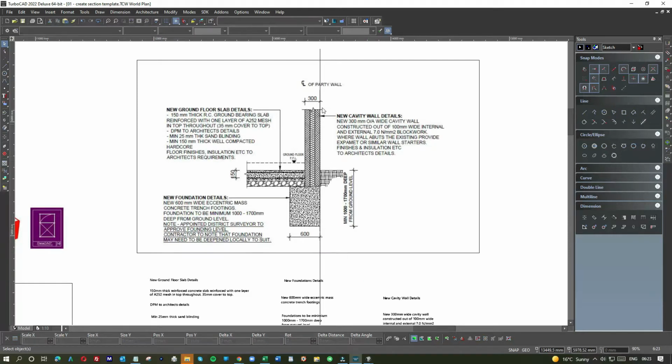Eccentrically loaded foundations are used where, under the party wall legislation, you're not going to put foundations into the neighbour's property to hold your wall. So you're building up to the party wall line, or the boundary line, which is here. That's your wall there, but as you can see, your foundations are also on your land or within your space. So they're a little bit special because they need to be a little bit wider and they need a little bit of steel reinforcement on them.